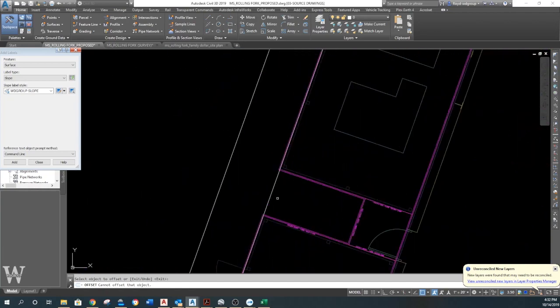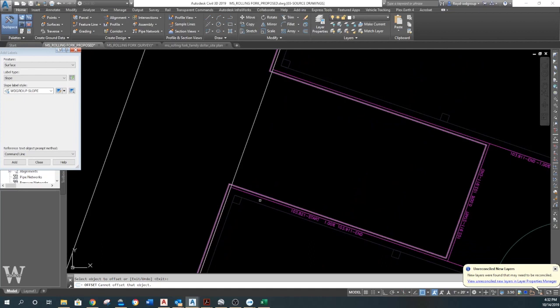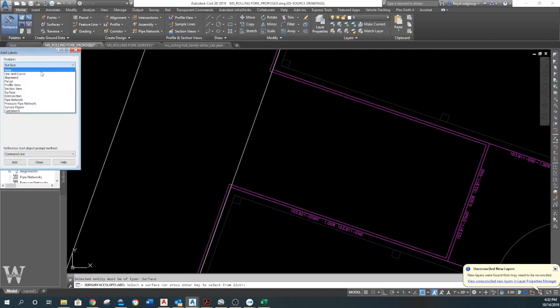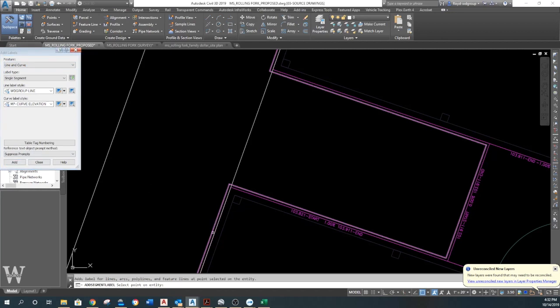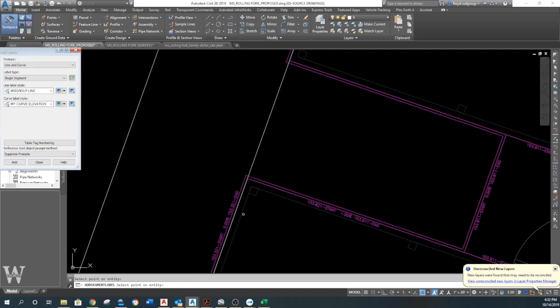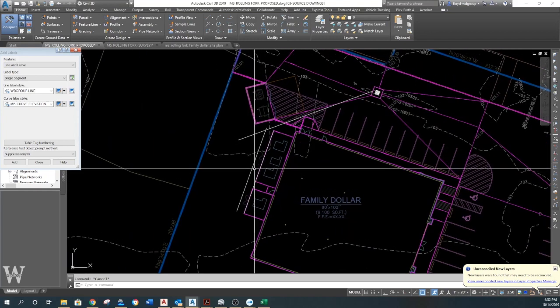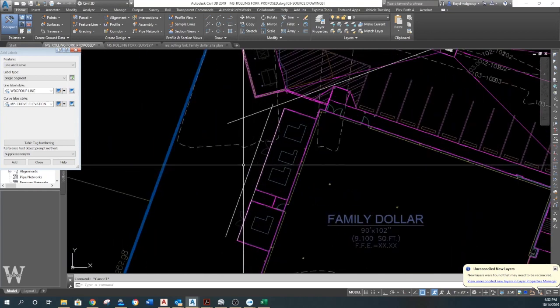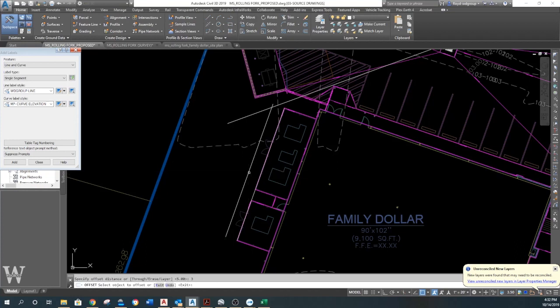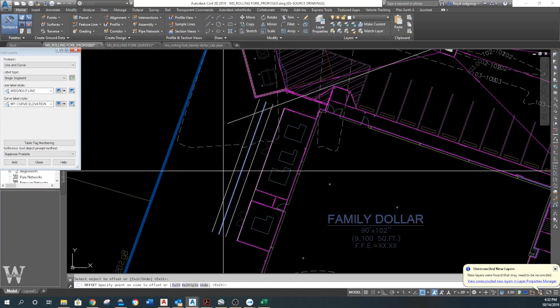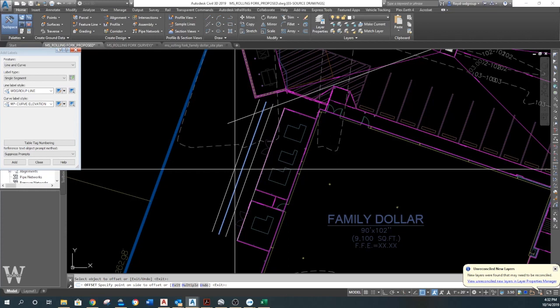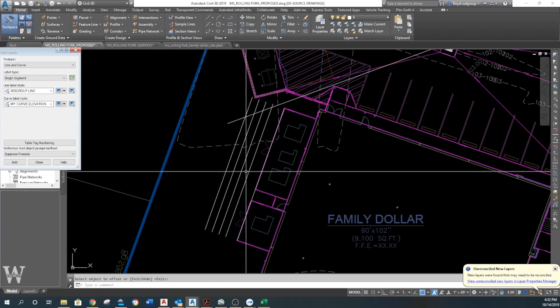I'm going to offset that 5 feet, and if you remember, that was, oops, go back to lines. The bottom of that is at 103.21. So if I come off 5 foot, I sloped a couple %. So that's pretty good. 3 to 1 gives me 2. That's 103, 102, 101, 100. That gives me a 3 foot deep pond.